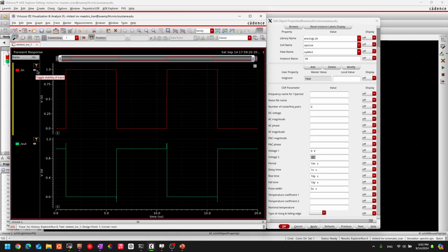So this is the input, or the pulse voltage we gave to the inverter, right? What I did here when it did 0 and 1 volt, it is actually this voltage. So basically the first voltage you gave it, and the final voltage would be the higher level, or the logic 1 of the pulse voltage itself. If you do 2 volt, this would have gone to 2 volt up.